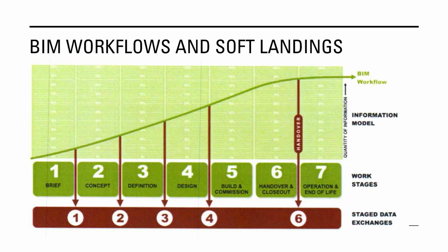A key milestone is the handover point between construction and operation. Traditionally, this was a chaotic data dump, but with BIM, we adopt a more strategic approach, often referred to as soft landings. Soft landings means the facility manager is involved early, helping define what data is needed and how it should be delivered.